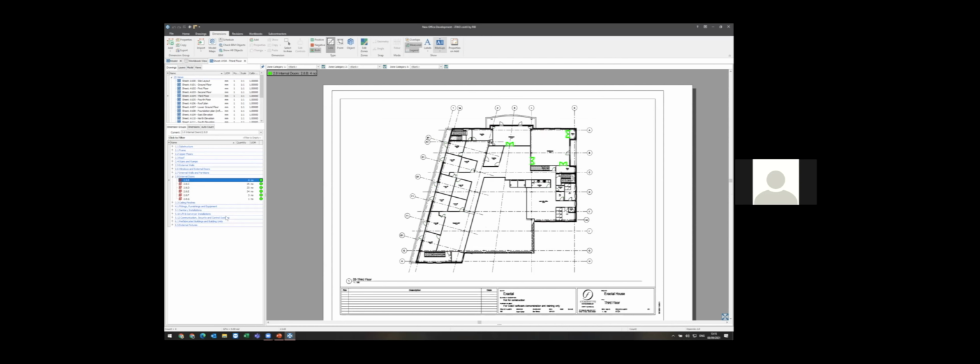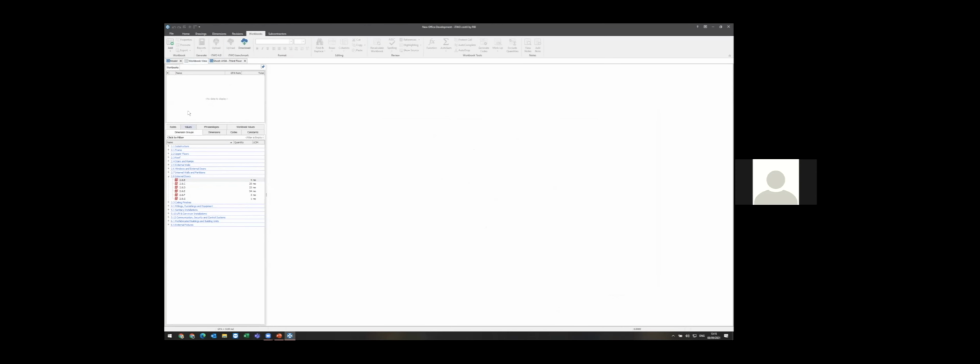So once we're happy with this takeoff process, we can jump across to the workbook view. And currently there's no workbook within there. So I go to generate a workbook from the dimension groups. I give it a name, so let's just simply call it the estimate. I tell it which rate library I want to use, so let's call it something like this, usually NRM1 rate library. And the descriptions are going to come from the rate library, so it's going to replace 2.8.b with the correct description for that item.